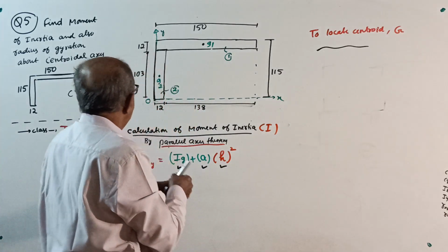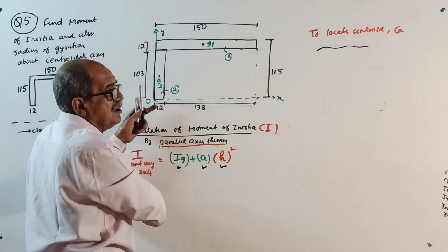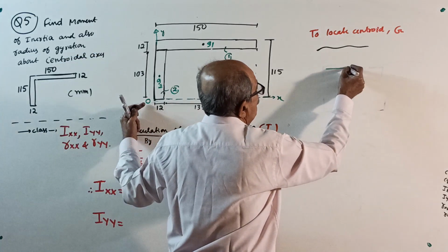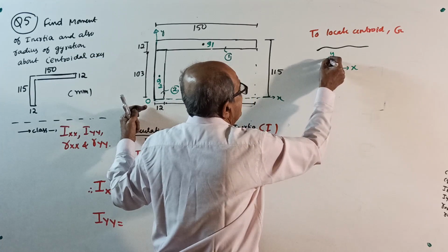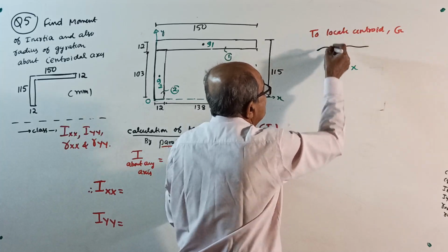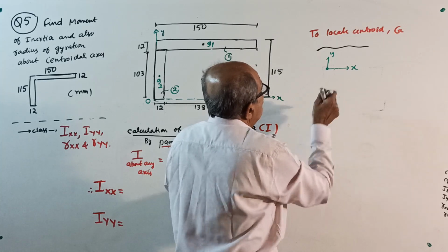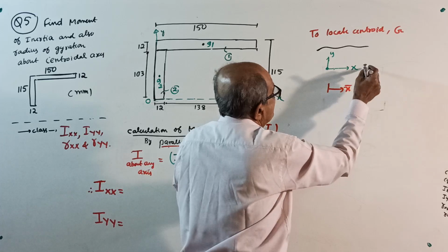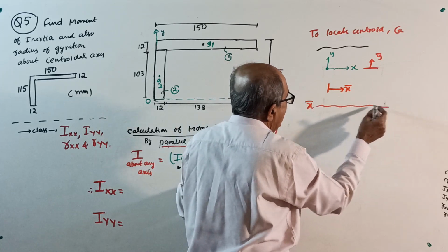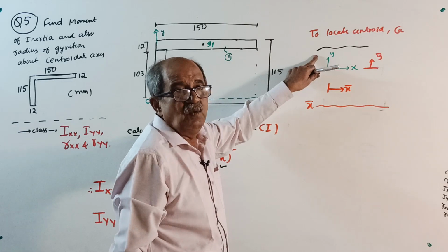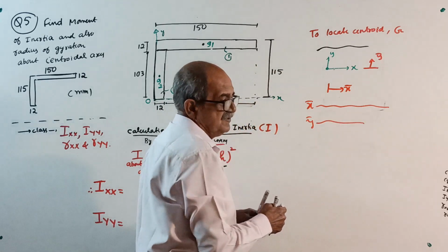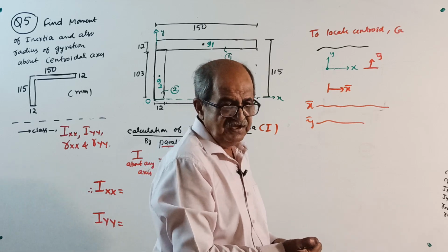Consider the reference axis passing through O, the bottom left corner. I told you earlier about the other methods, leave it now. See, O is the reference, OX this way, OY this way, through this point. Then from the OY axis you find x bar, and from OX you find y bar. Write the formula for x bar from OY equal to A1, and also write the formula for y bar from OX. These you all have to write. If you are serious, you will write.